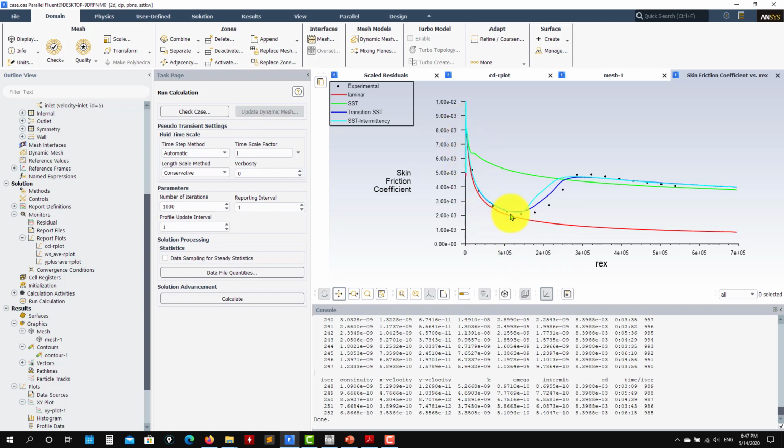See, the dots here are the experimental results, and then we have different simulations. See that we're running laminar, DNS in theory, and it is correlating. Basically, just to explain what we have here in the experimental results: first we have a trend here that is going laminar, and then you have the laminar flow, and then you have the onset of the transition to turbulence, and then it switches to turbulence.